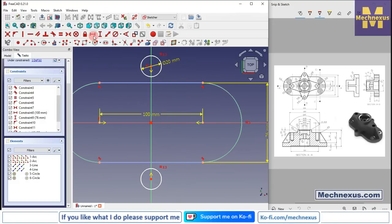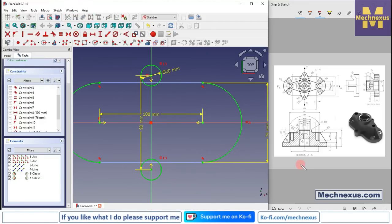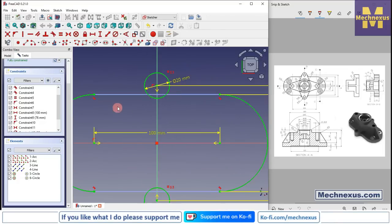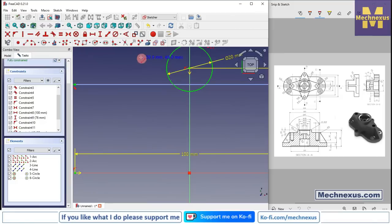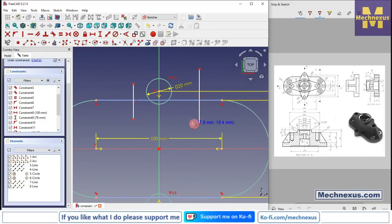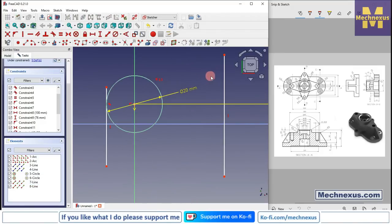and distance between is of 90 mm, and now we will select line tool and draw the two vertical lines, and select this and add a tangency.